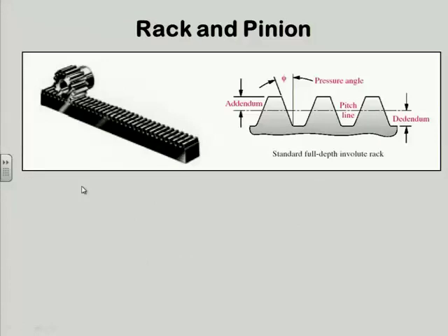The rack and pinion is another common application, and the rack is nothing but a gear that has been made to be infinitely large in diameter or radius. Thus it becomes a straight line. And if you want to generate an involute on the rack, then I have to send you out to infinity with the string and the piece of Scotch tape to stick it on there so I can put the pencil at this end and lift it up, right? So it's coming off a straight line, and I get a straight line. So the trapezoidal tooth that results from my involute generation on a flat gear or rack is a pure trapezoid.